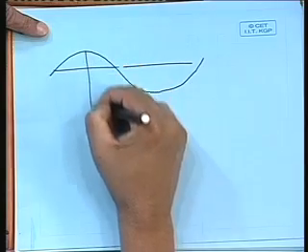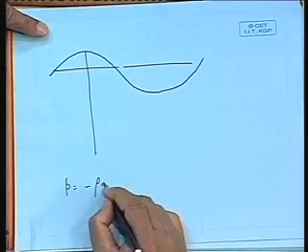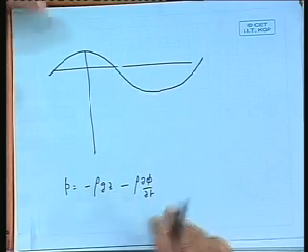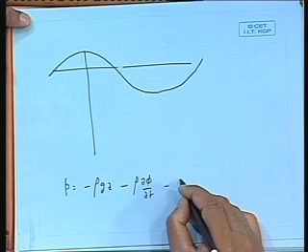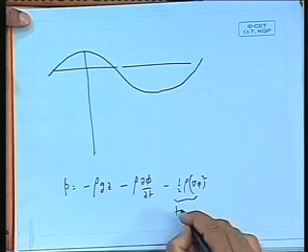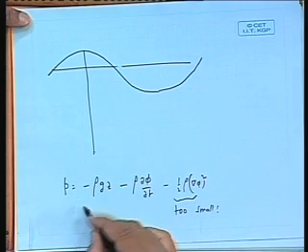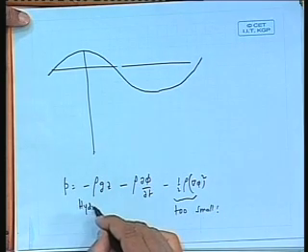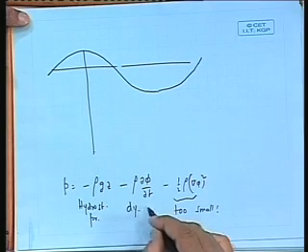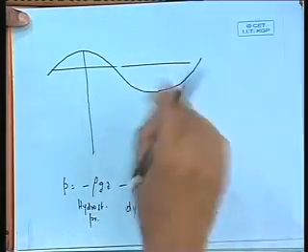Now what happened? Remember that pressure is given by minus rho g z minus rho d phi by dt. Now rho d phi by dt is minus half rho del phi squared. This part I am neglecting, too small. This part is hydrostatic pressure and this is dynamic pressure. You can call this the wave pressure. Okay. Now, let me see how it varies.